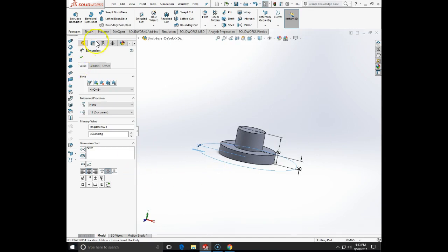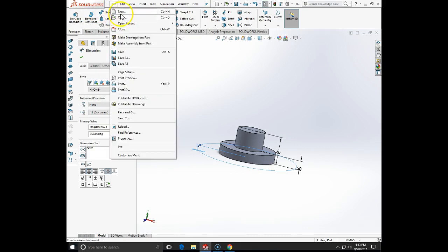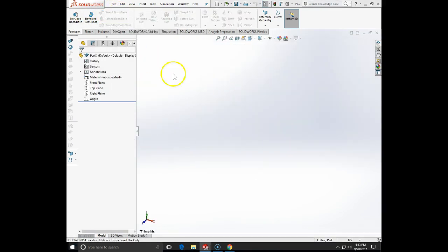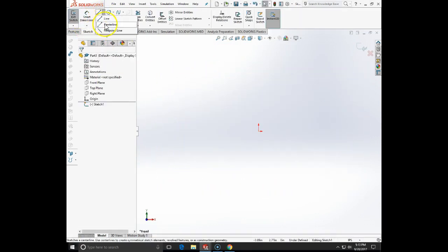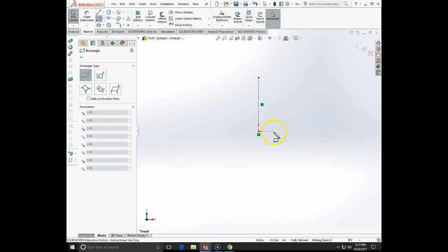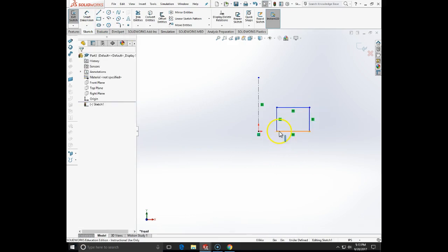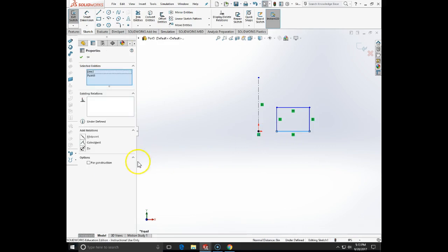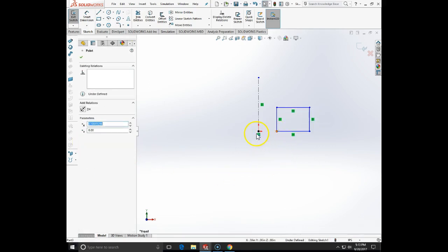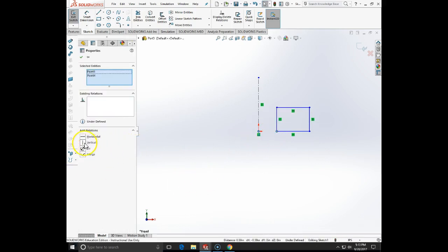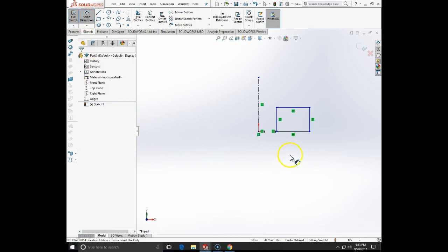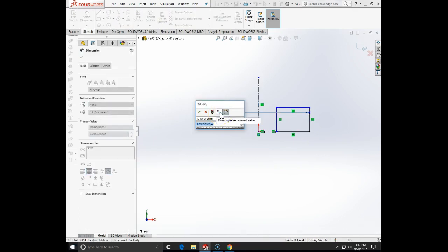Now I'm going to make the top of the block as a new part. And the top of the block, again, I will take it on the front plane. I will make a vertical center line. And I'm going to make a rectangle whose bottom is aligned with the coordinate origin. So the 2 points are in the horizontal. Going to specify the outer diameter to be 120 millimeters.